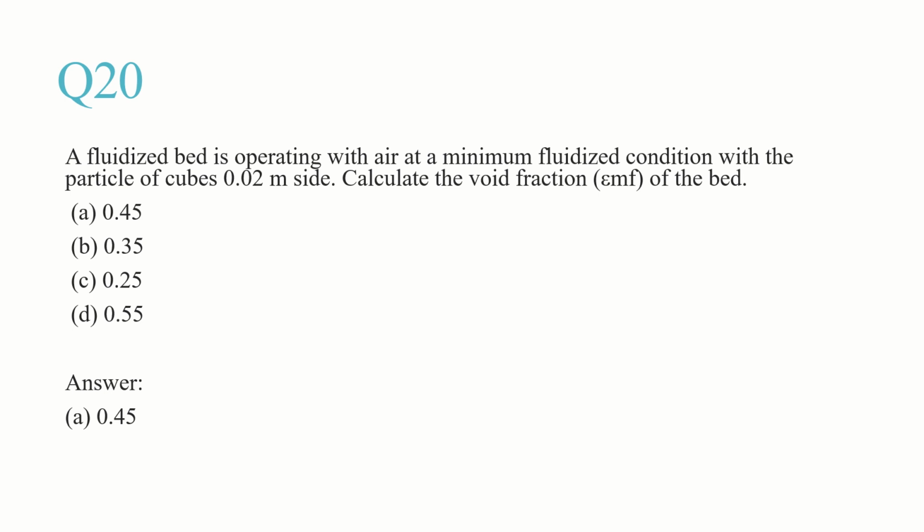The void fraction of the bed is, actually this is an incomplete question. We cannot calculate the minimum void fraction with this data, but in general the packing fraction of the cube is 0.6. So the void fraction at the tightly packed condition is 0.4.